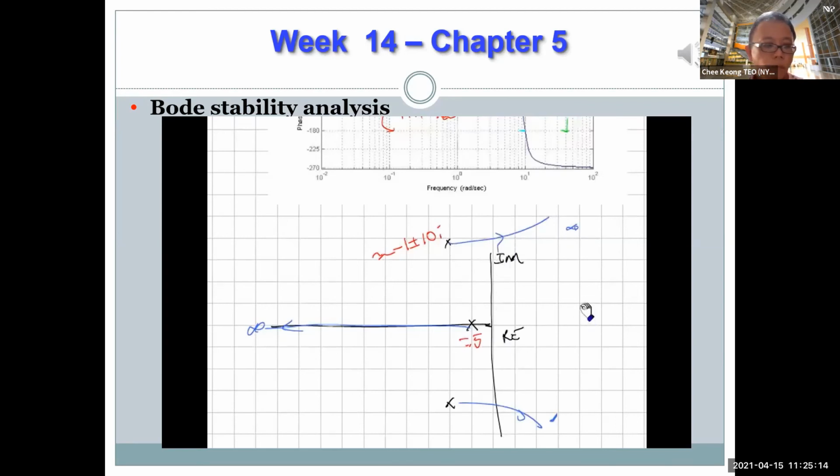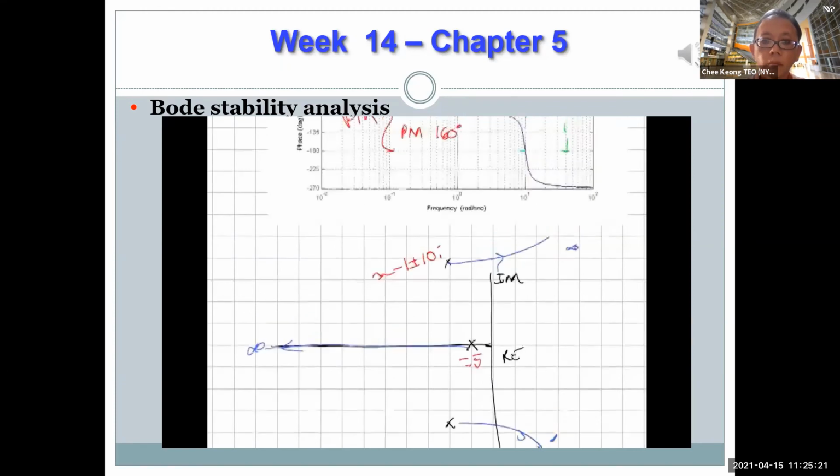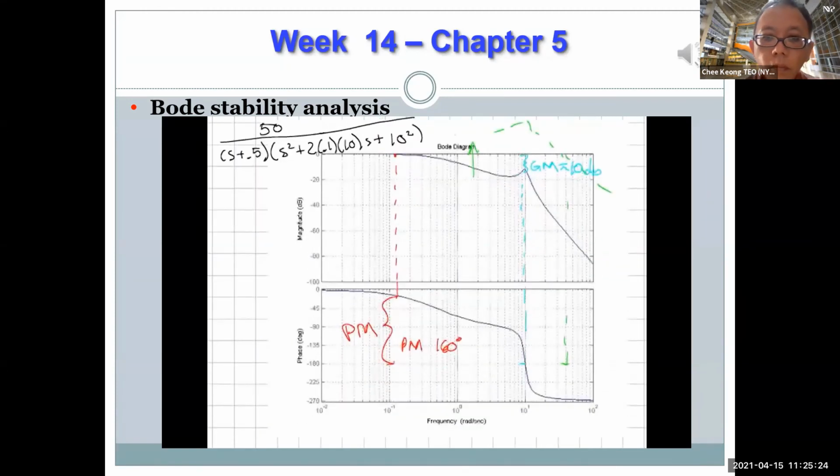Now, the root locus tells you that that happens, but what it doesn't tell you is what value of gain would be required to make that happen. If you go up to the Bode plot, you can actually calculate the gain required to make the system go unstable. In this case, if we look at 180 degrees of phase right here, and we go up, we see this gain right here. If we increase the gain by that amount, then we'll have a negative gain margin, and the system will go unstable. So it looks like if K is somewhere around 15 dB, the system would be unstable. I'm going to go through and just verify that.